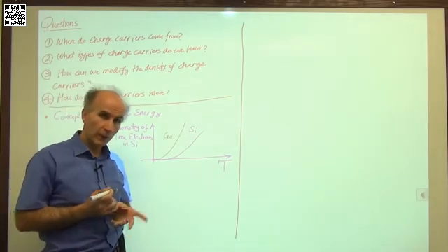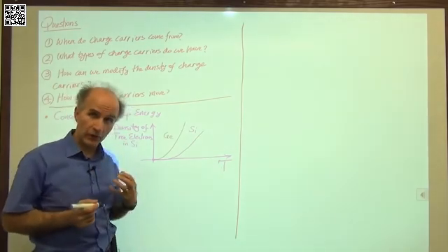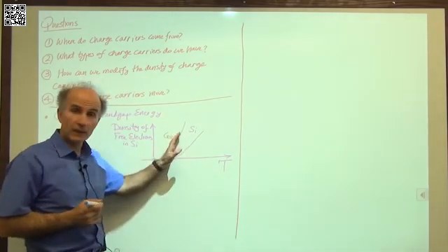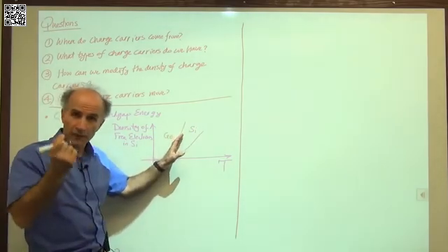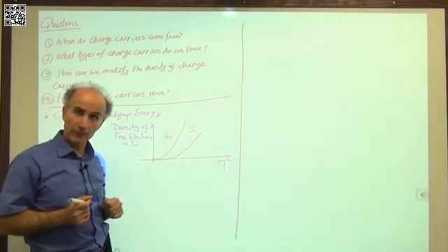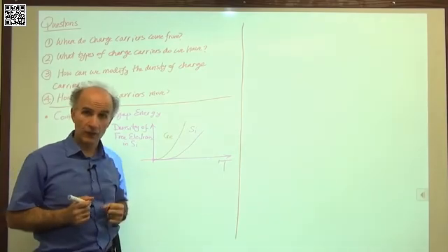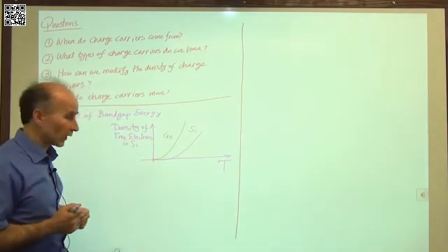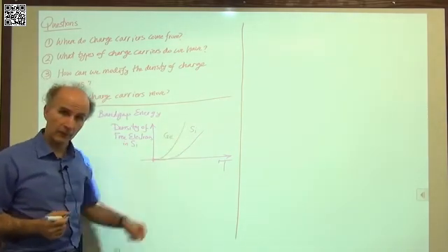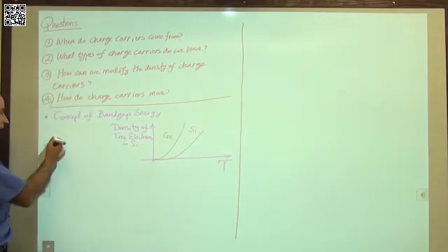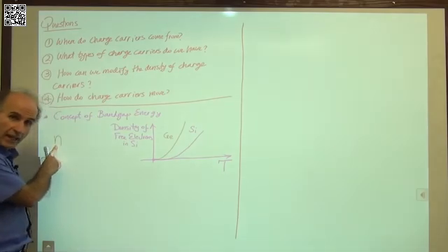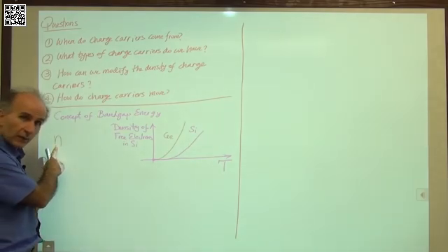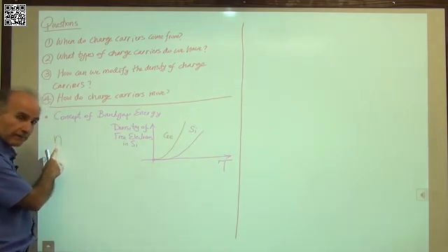Okay, so we are hoping that maybe there's one equation that can describe both of these, and there's only one number in there that depends on silicon or germanium, right? And in fact, that equation exists. So we'll try to write an equation for this behavior. So here's what we'll write. We'll write the density of electrons. We'll denote that by n. N is the number of electrons per cubic centimeter.